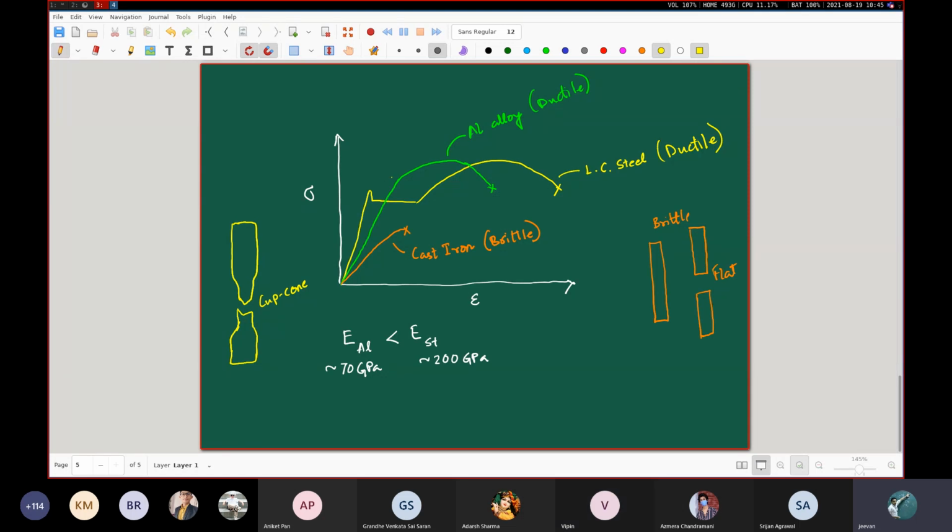Thank you. So yes, these diagrams you see are for stress versus strain. And the reason that we plot these diagrams for stress versus strain and not force versus length is that very same reason: when you draw something for stress versus strain, it is independent of the initial dimensions of the material. It is independent because this epsilon value is a relative change in length. It is not the absolute value of the elongation. It is rather the relative value of the elongation, whether it is the true strain or the engineering strain. That relative elongation may be calculated in different ways, but it is after all a relative elongation. So it is kind of like a normalized value.